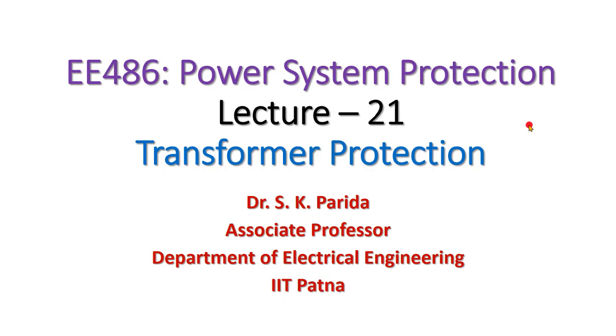Then we will talk about other faults and abnormal conditions, like if there is inrush current, how the protection scheme will behave and what modification we need to make, and also about the high resistance earth fault and how it can be protected.